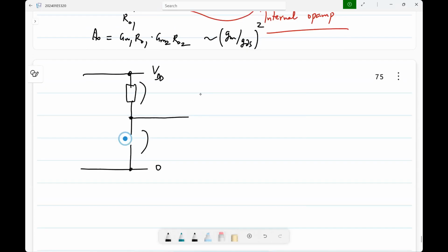So basically, the best case would be you have just one PMOS transistor on the upper side. I'm not showing any specific circuit here, but just to be able to drive that, you need to have that and one NMOS transistor on the lower side. So you need to maintain, I hope you are familiar with this notation, this is VD sat of N at whatever current it is operating, right? And similarly, this is VD sat P.